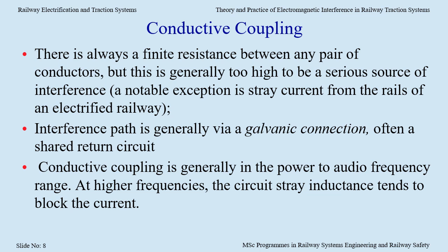Often it's a shared return circuit. Conductive coupling is generally in the power to audio frequency range. At higher frequencies, the circuit stray inductance tends to block the current.